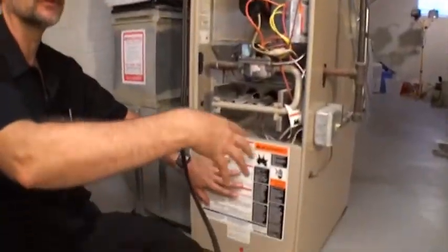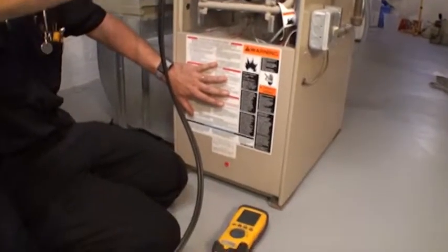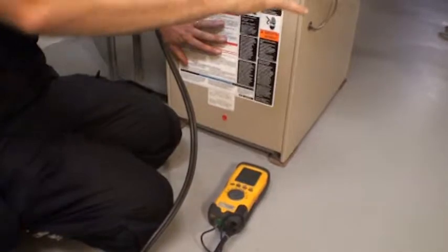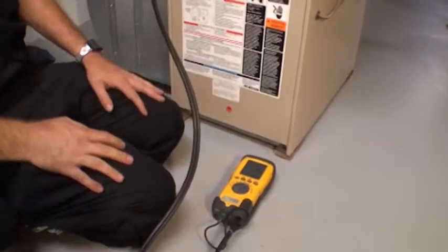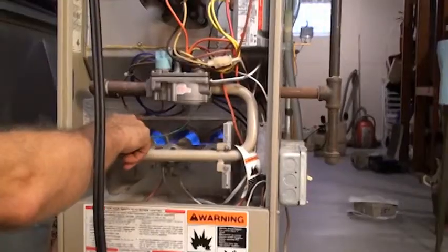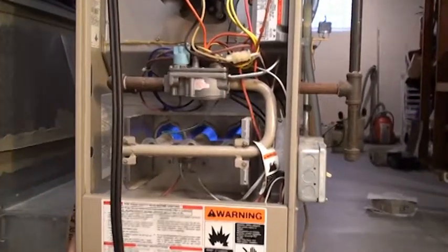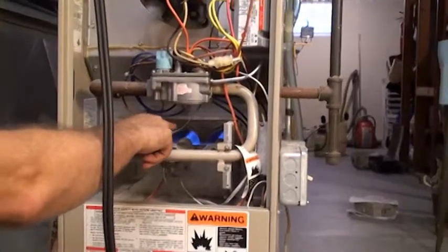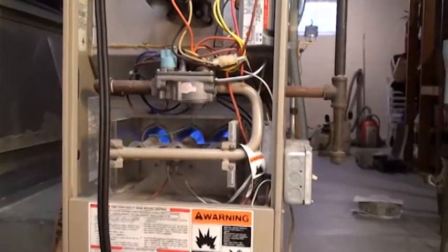Upon completing the visual inspection, Community Action expects you to perform a combustion analysis check of the heat exchanger, watching for an increase in oxygen and/or change in carbon monoxide once the blower turns on. You should also be watching the furnace burner flames when the blower turns on to see if they move around. If a crack or a positive heat exchanger test is discovered, you must stop all work and call Community Action.